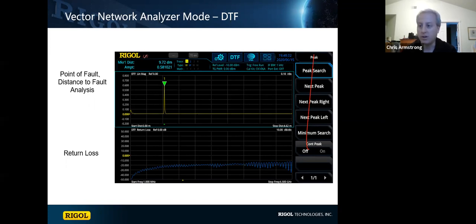So as long as you know what the velocity factors are, or obviously you could set a cable length and then tweak it to match, so you debug the velocity factors. But that's how the math is done there. Those are the big levers to pull, the velocity factor, which is really a material science calculation.